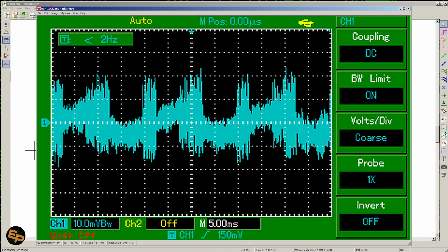100 kilo ohm resistance, or input impedance. I needed to switch to 10 millivolts vertically, and we see that along with these periodic spikes, which are probably also from the power supply, we have about 3.5 divisions, so about 35 millivolts peak to peak, give or take.